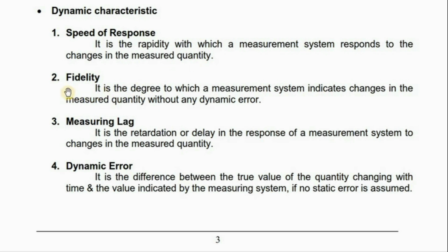Okay, now the next one is fidelity. What is it? It is the degree to which a measurement system indicates changes in the measured quantity without any dynamic error. Here, suppose again that a quantity is continuously changing with time, in the form of a sinusoidal waveform.